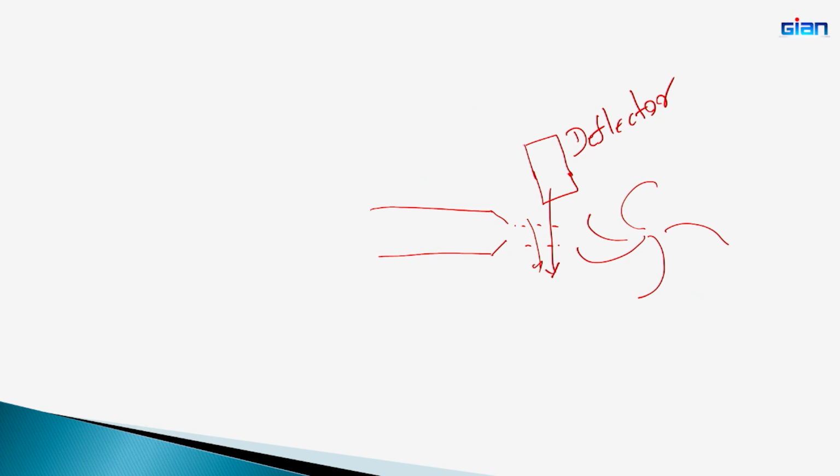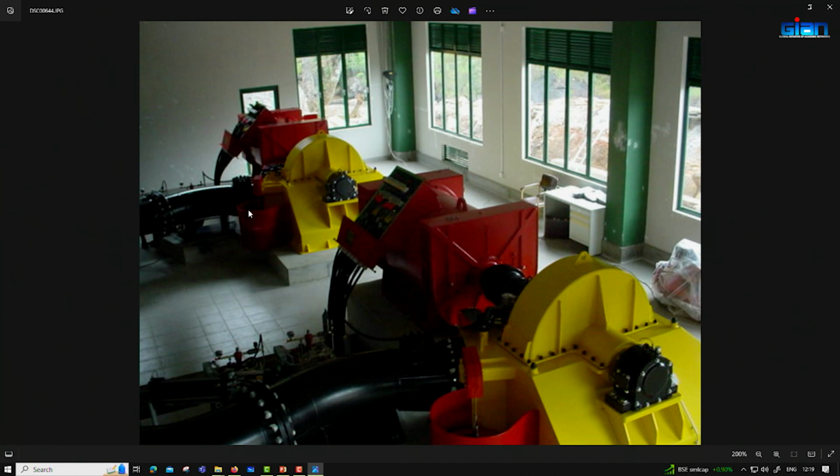So, the deflector operates by this weight. You can see both are having this weight, right. When the electricity is there, it is lifted up automatically and kept at a higher point. The moment the breaker trips, it drops, and by that weight the steel piece comes down, right, and deflects the water away from the turbine, avoiding any overspeed possibilities, right. Okay.